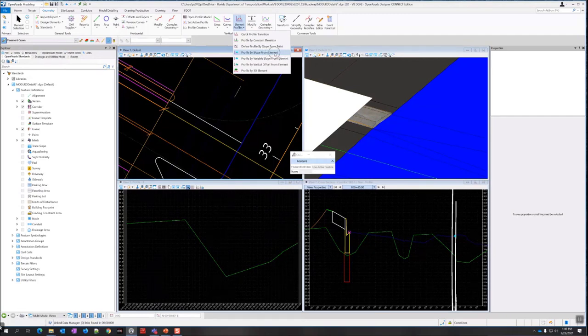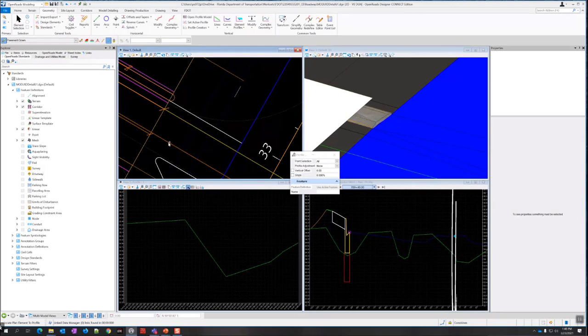So this one option here, to go under the vertical section, element profiles, click the drop down and select profile by slope from element. So it says locate planned element to profile. Let me bring up that command again. I don't know why it's not letting me.